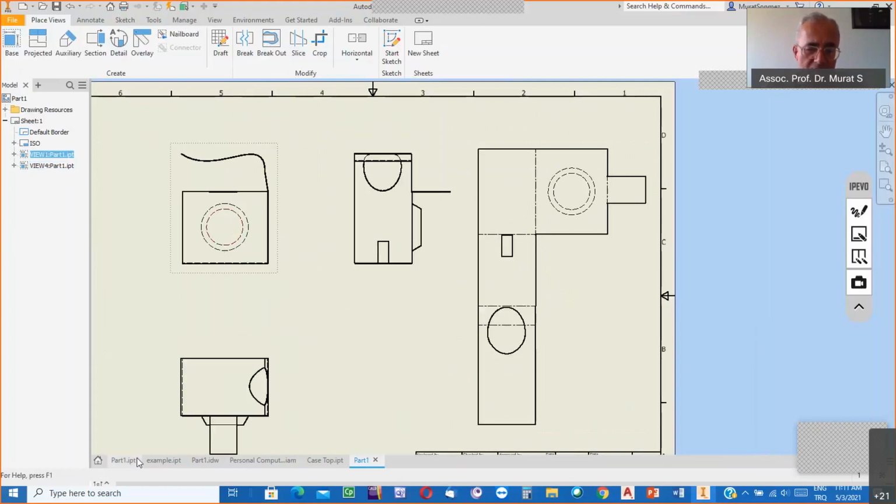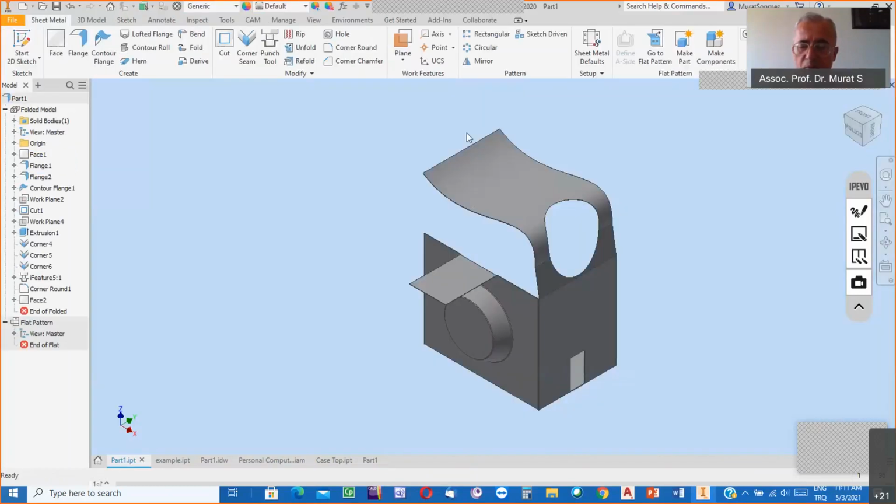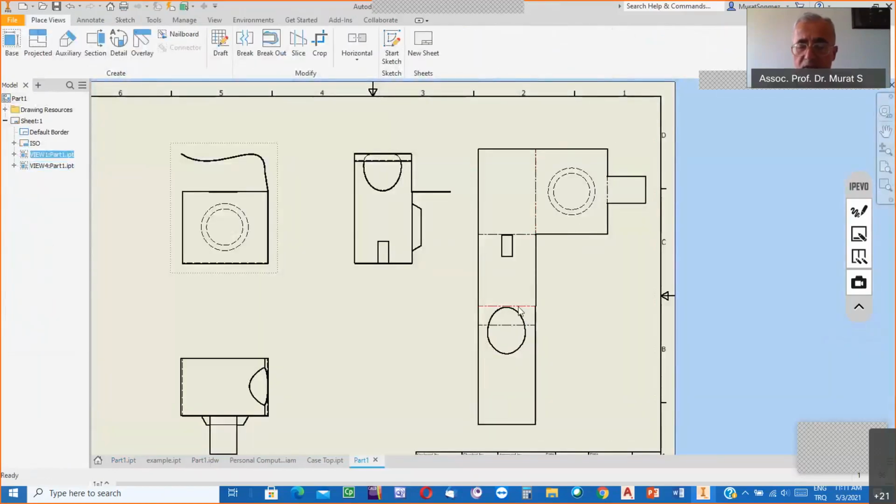To be able to have the sheet metal component in this shape at the end of the folding process, like this, then yes, here, well, along this edge, along this path, sorry, path, and this path, the sheet metal is to be folded. Well, this is going to be the question of the technician. Okay, sir, well, I see that this is just a folding line, but what about the folding angle? Whether this part is going to be folded 90 degrees, 40 degrees, 30 degrees, well, it is a reasonable question, and it is a challenge actually to say something looking at this view.